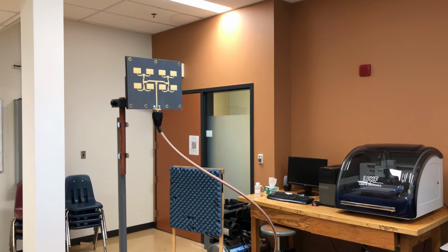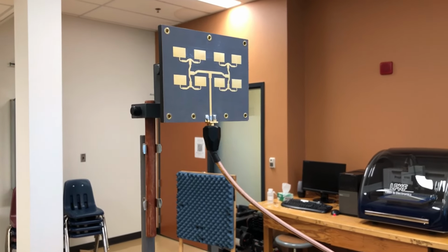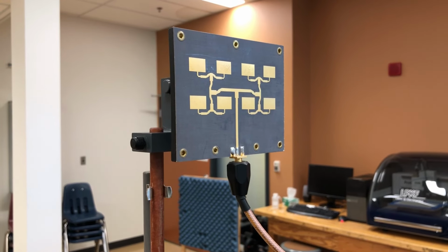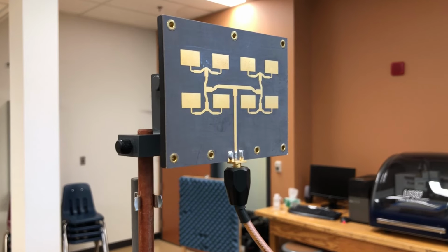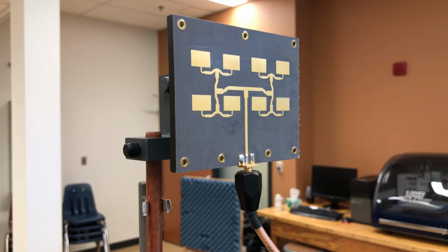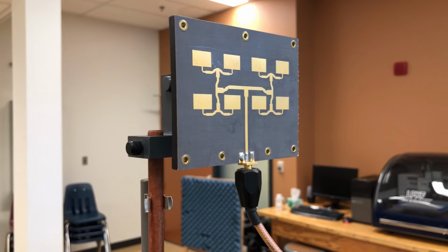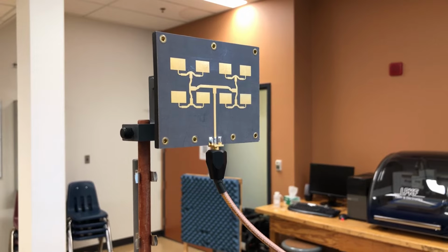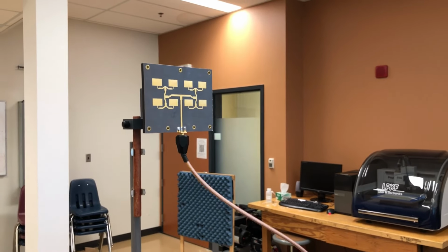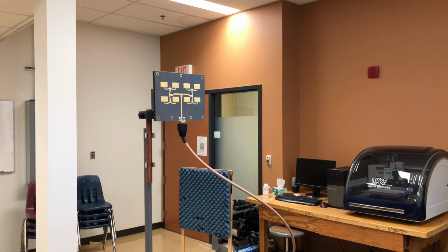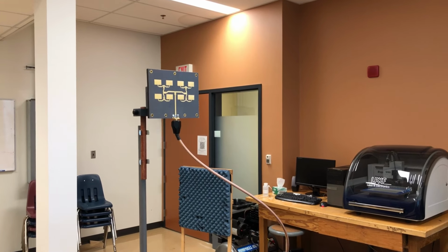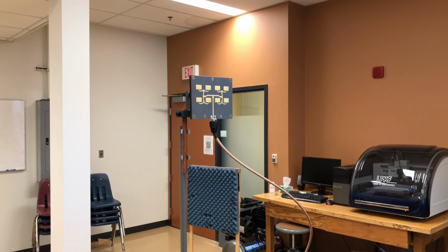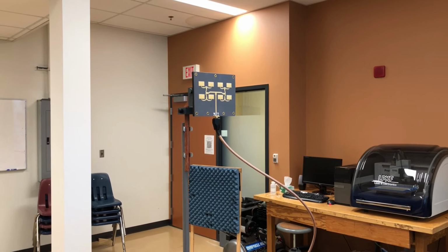So I'm going to have a closer look at the antenna so that you can see it better. We have 4 elements on one side, 4 elements on the other side. We have our transmission line, we have our power splitter, we have our quarter wavelength transformer. The other thing to note here is that according to the LabVolt manual, we have separated the patch array from the horn antenna by 1.6 meters. So let's start our measurement to find the H-plane pattern of this antenna.